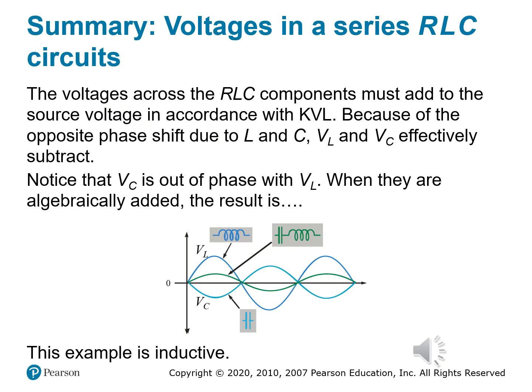That's right. Opposites don't attract here. They cancel out partially, right? So again, my reference to the Matrix, Neo and Agent Smith being complete polar opposites. If you didn't catch that mathematical reference in the movie, go back and watch it. So the result is a net reactive voltage that's smaller than either alone, but still enough to make the system inductive in this particular case. That's because X sub L is greater than X sub C, and the net behavior tilts toward the inductor's lead. So why does this matter? Because every RLC voltage waveform must add up to the source voltage, even if some of the components are out of sync.